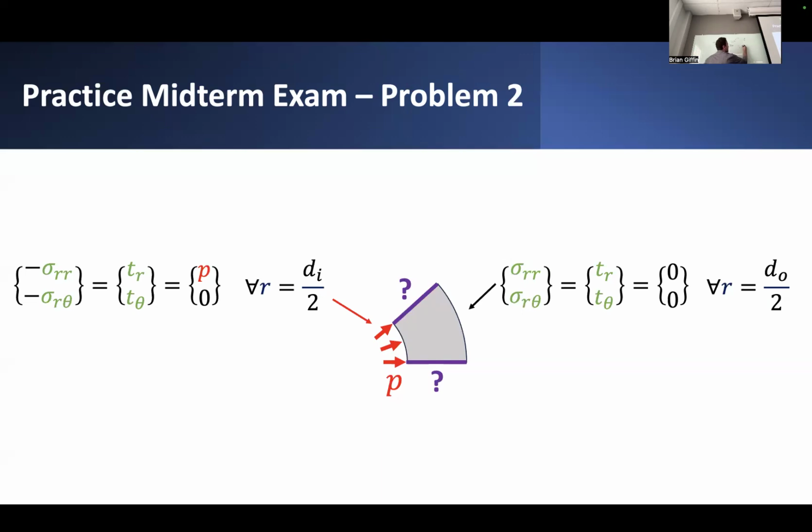The components of traction are given by this relationship. Assuming you have some normal direction n, and you have some components of stress defined in whatever coordinate system you've chosen, then the resulting components of traction, a vector, are obtained by this matrix vector multiplication.